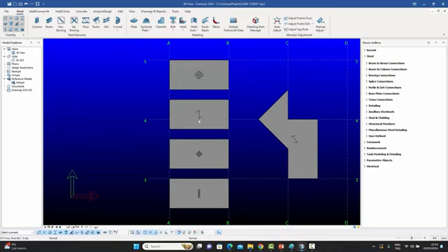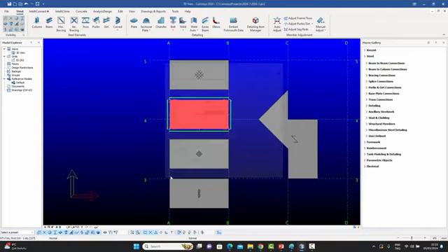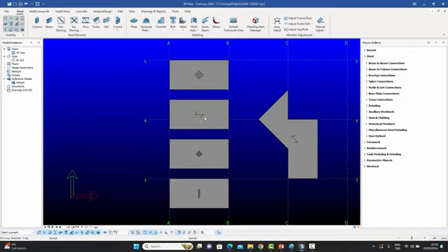This is the grating symbol, as you know, and this has also been now provided for the modeling side as well. Once again, we have whether we want to draw the symbol or not, but we can also choose whether we want to place it in the short direction or in the long direction. So on the modeling side, we can show the direction in which the grating will be designed. So the user now has more control over this grating symbol, which can then pass on this information to the fabricator as well.